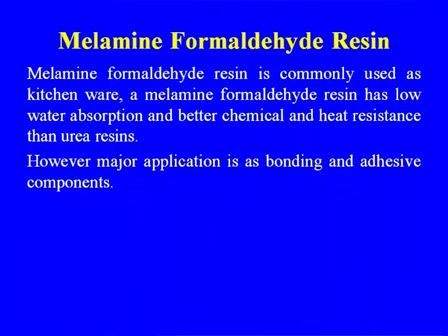So, the importance of melamine formaldehyde: I told you earlier that with the coming of melamine formaldehyde, it replaced almost the stainless steel in kitchenware and other kitchenware material. So, melamine formaldehyde resin is commonly used as kitchenware. Melamine formaldehyde resin has low water absorption and better chemical and heat resistance than the urea resin. However, the major application is as bonding and adhesive components.